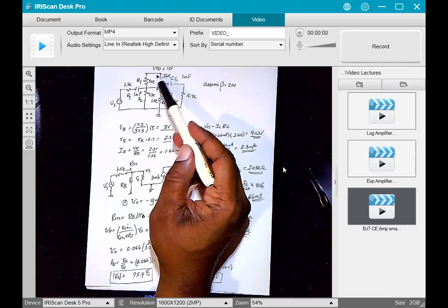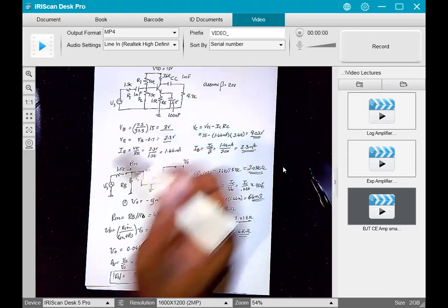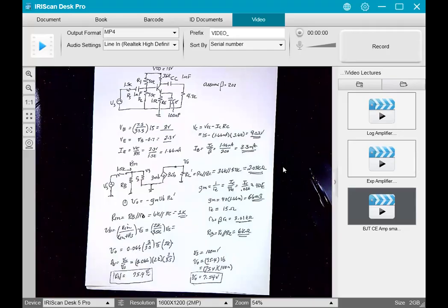So now if I make the amount of standing current less, then the thing can run longer on a standard battery. Yeah, all of these are degrees of freedom that you get to play with when you're doing analog design. Okay, so here's my gain. And if we had 100 millivolt input, then we get 7.5 volts on the output.